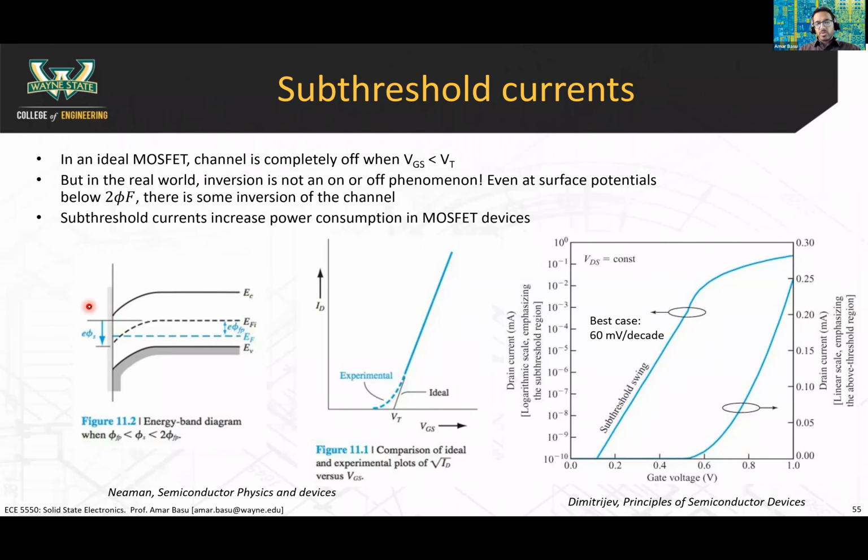So even when you're below the threshold voltage, VT, your channel is still going to be there. It's just going to be weaker. That's what we call the subthreshold regime. Even at surface potentials below 2 phi f, there's some inversion of the channel. And so subthreshold currents are important because they increase the power consumption of devices. If you're at a gate voltage below VT, you expect your device to be off. If your device is not completely off and you're flowing current between the drain and the source, of course it's going to create power consumption. That will decrease the battery life of a device.